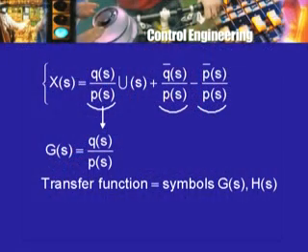Now, what information can we get about the system behavior from the transfer function? That is what we would like to look at for a little while. Remember, we are not going to look at frequency response, that will come later. Now, to get that information from the transfer function, it is useful to factorize Q(s) and P(s) into linear factors, and that's what I had done earlier for our numerical example. We factorized Q(s). Of course, Q(s) was first degree, so it came already in a factored form, only one factor, whereas the denominator was of degree 2, so it required some factorization.